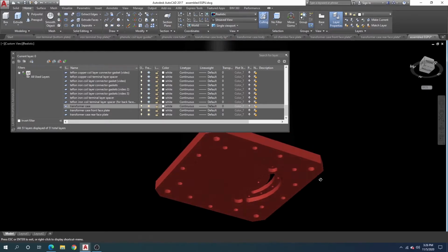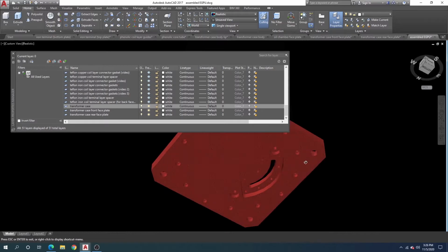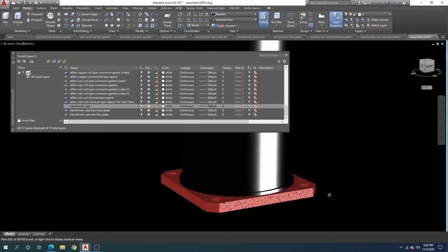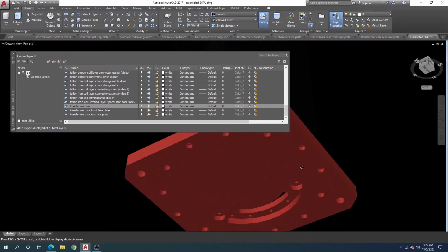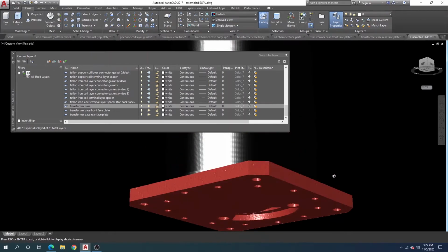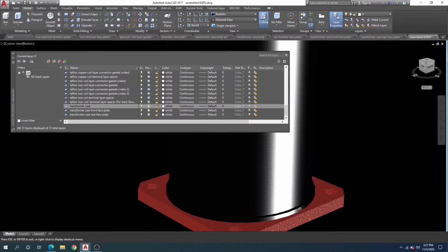And the screw holes here, as you can see, these bolt holes, the bolts will go through here. They're counterbored. These are the counterbores right here, as you can see. Okay, so the bolts go through there, and you have internal threads in the lip of this case.